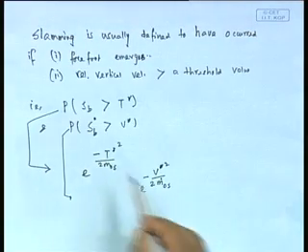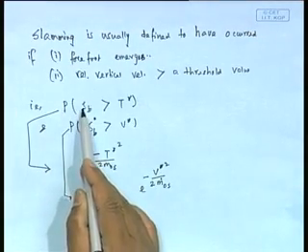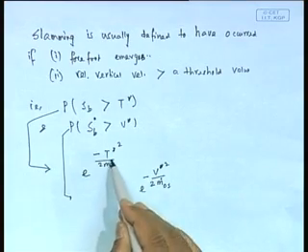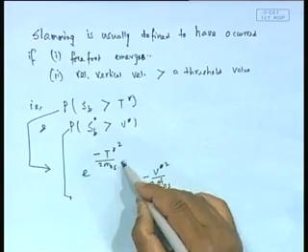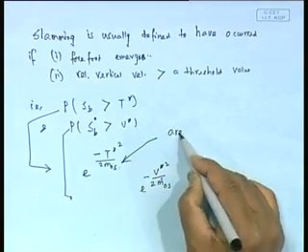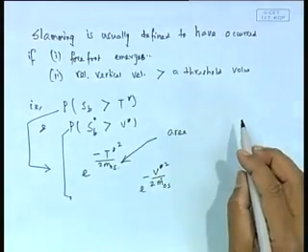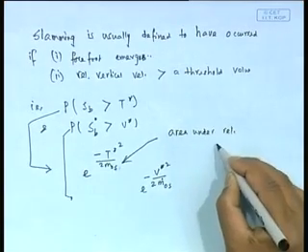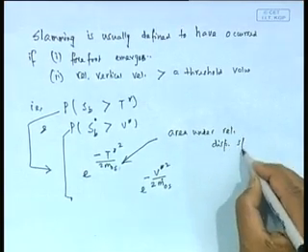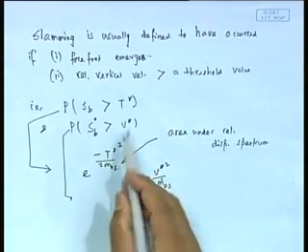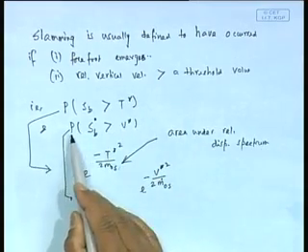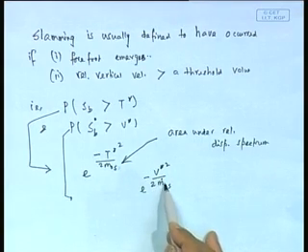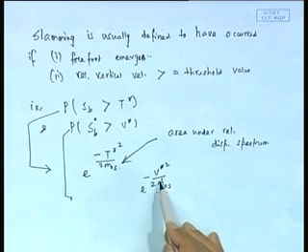See here what is happening. The probability that S B is more than T star is of course given by e power of minus T star square by 2 m0 S, and m0 is the area under the relative displacement spectrum. And this is of course the probability of S B dot more than V, which is e power of minus V square by 2 m0 dot S, which is of course the area under the relative velocity spectrum.